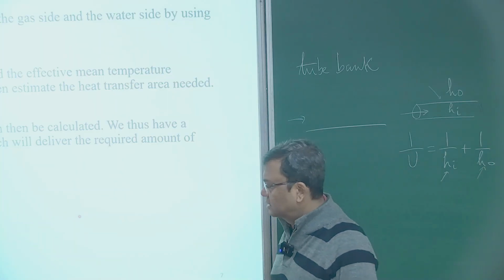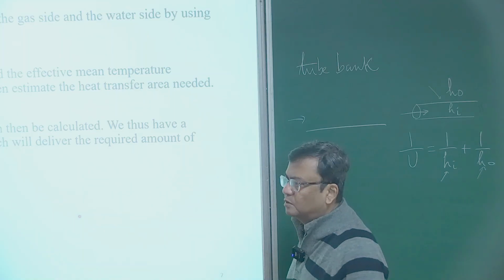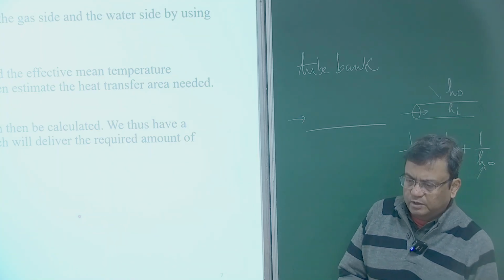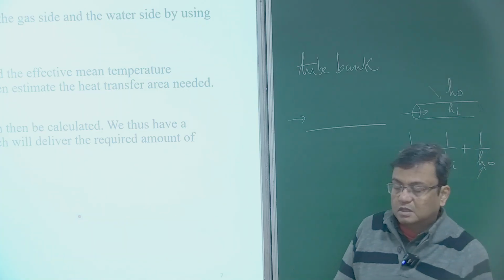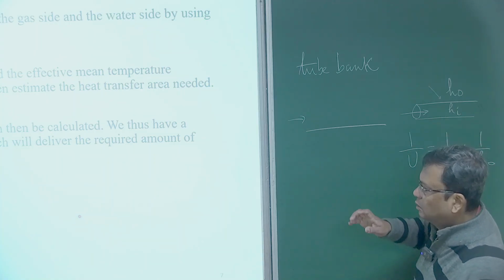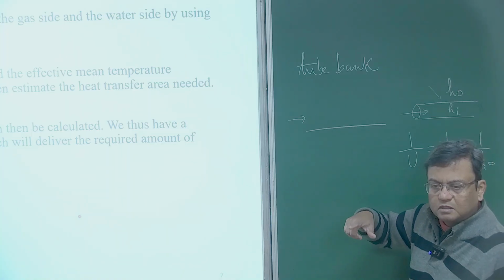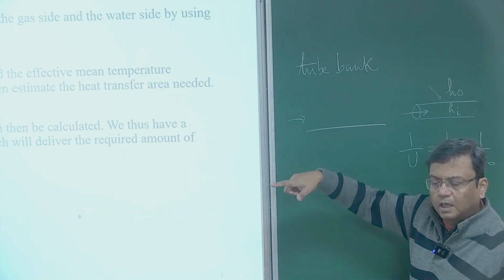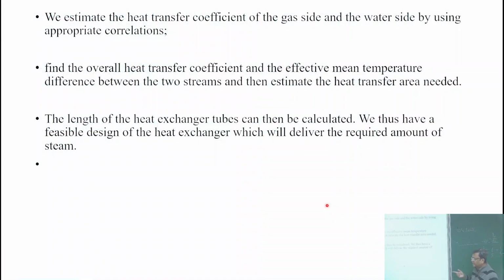And then that water, you wanted to convert that to, for those of you who came in the last class, 2-bar saturated steam, right? That's what we discussed. So you can calculate the heat transfer which is required to take the water from 10 degrees Celsius to the saturated vapor stage. And using that, you can also calculate what is the change in temperature of the flue gas, right? Because the flue gas entry temperature you know, and you know the flow rates of both these, isn't it? So you can do an energy balance and get all the temperatures.